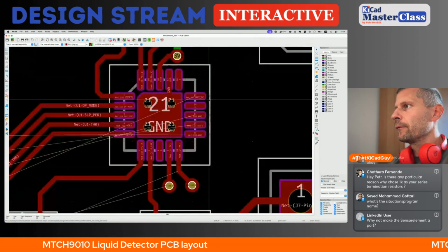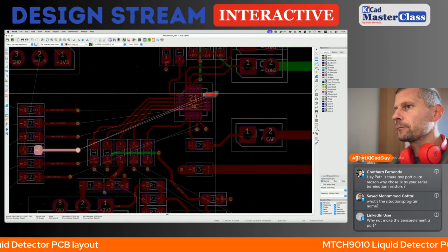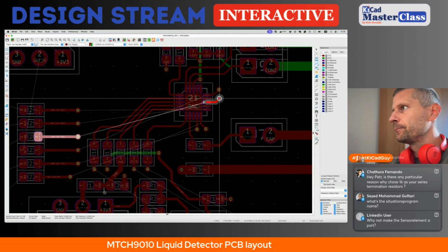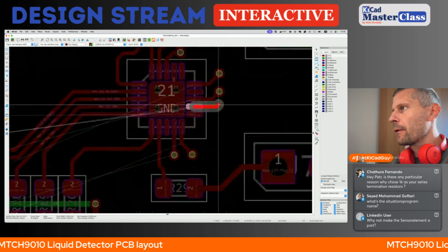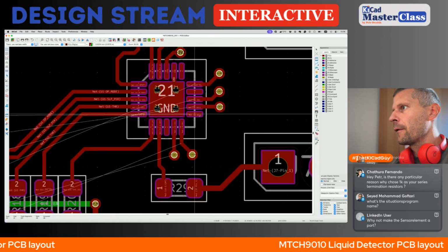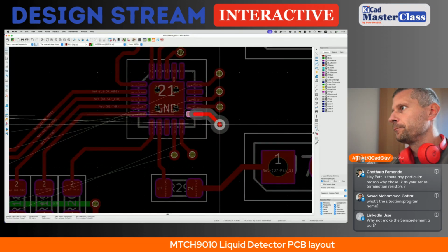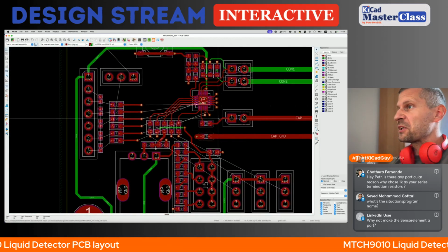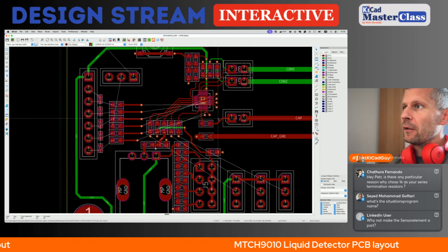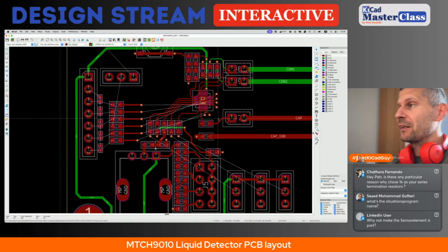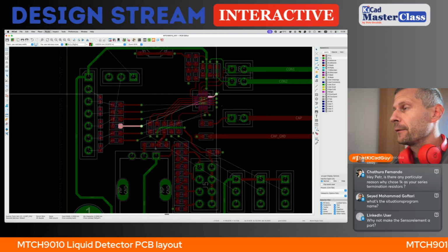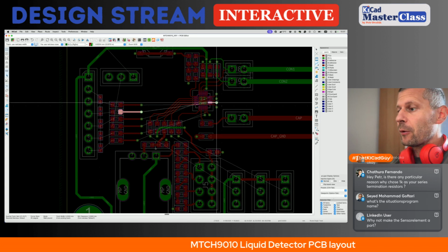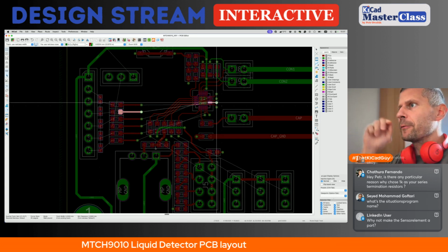So now these signals, all with vias, yes, looks good. The vias are plus minus evenly distributed, and as I said, if the traces are crossed, we can rearrange the pinout on the header, and probably we will.